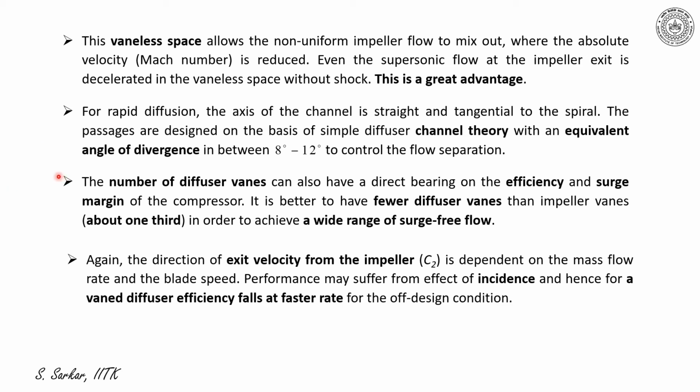The number of diffuser vanes can also have a direct bearing on the efficiency and surge margin of the compressor. Surge occurs at a higher flow rate when the vane diffuser is used than when a simple vaneless diffuser design is adopted.